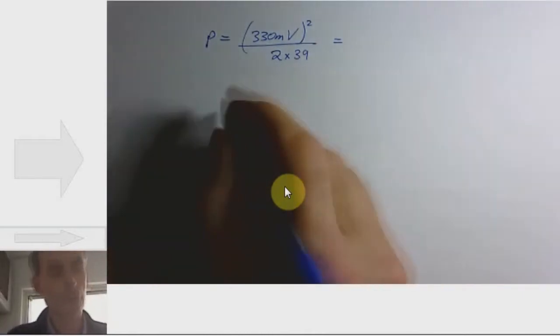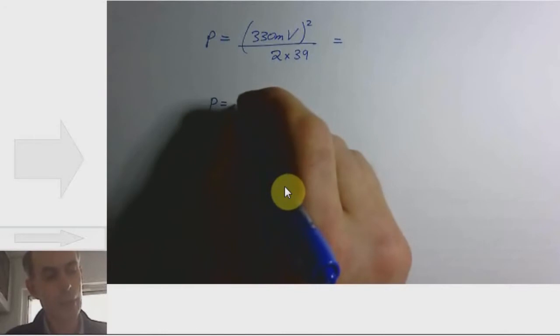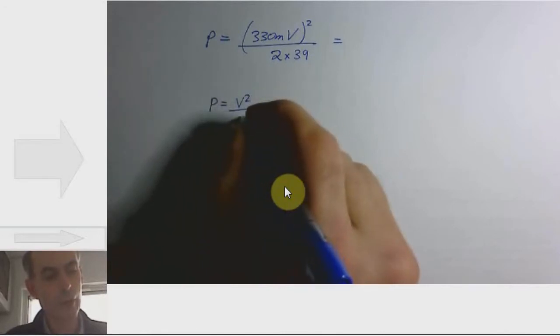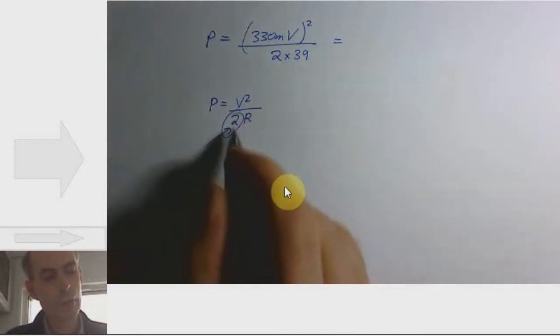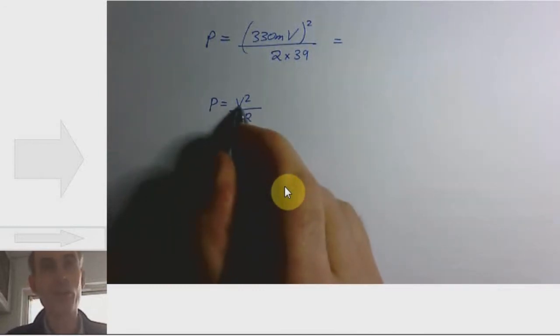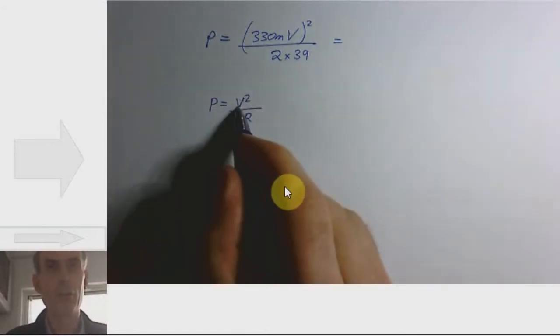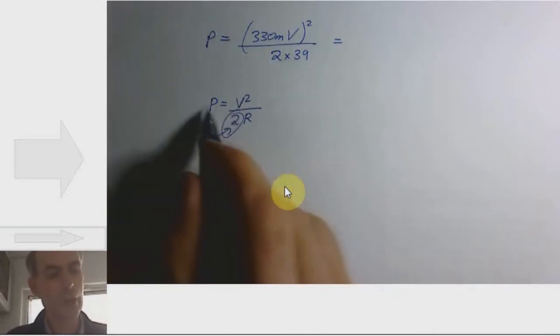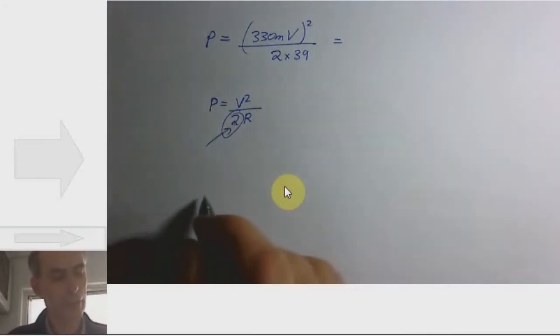It's really just the expression that we have from DC, power equals V squared over R, except we're having to put in that value of 2 because the voltage is not a constant value of V, it's a sine wave with a 0 to peak amplitude of V, and if we're interested in the average, the mean value of power, that factor of 2 arrives for that reason.